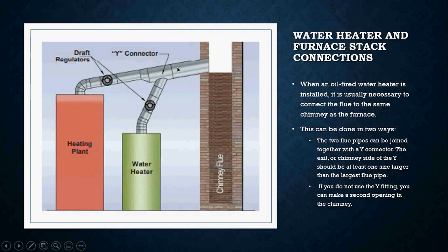My size is actually just 1 size larger than both of these. So if this is a 6-inch flue pipe, both of these are 6 inches, this one here is going to be at least 7.